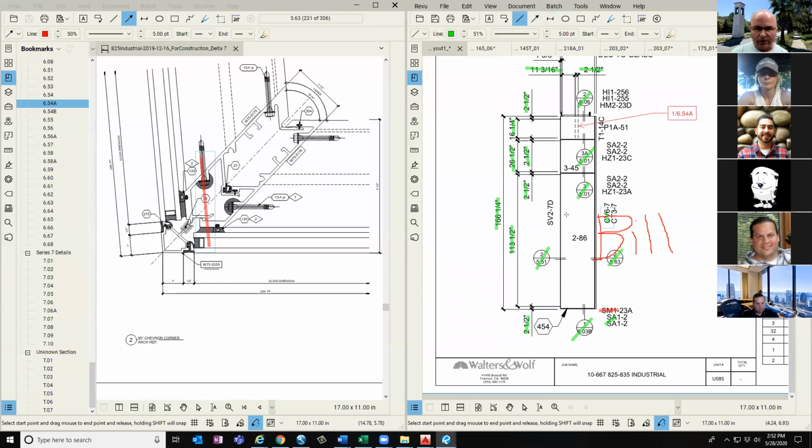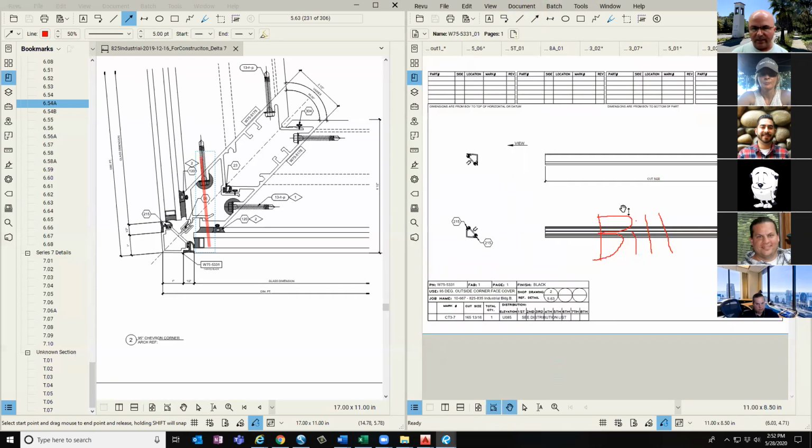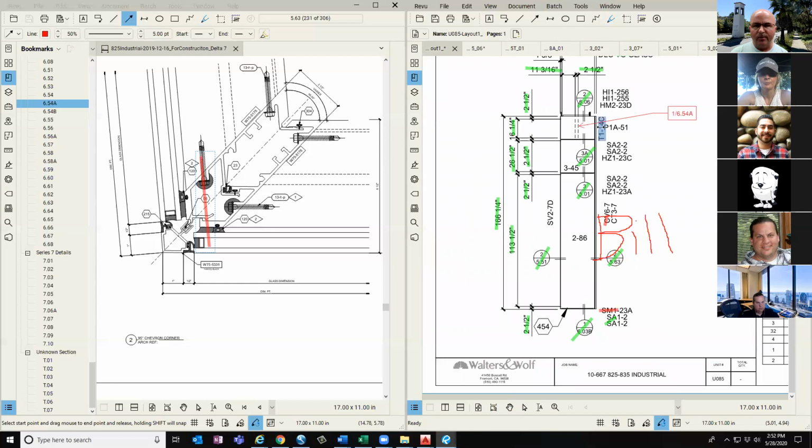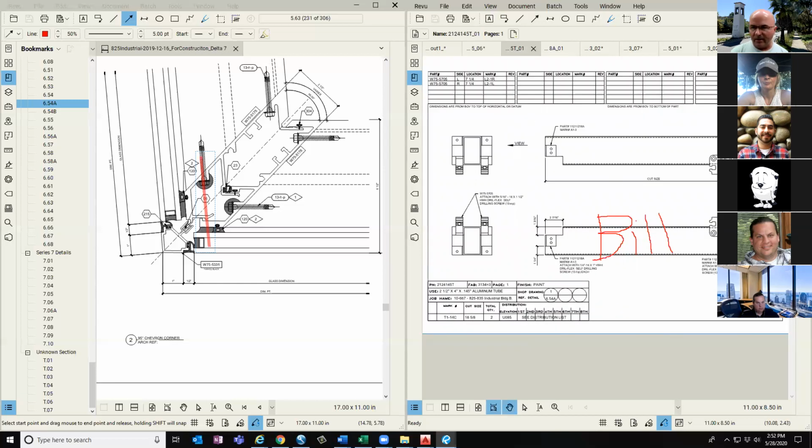Then I'll go to, this is actually red because it's got a problem with it. Then I'll look at the corner trim, verify the length of that. It's actually the same length as the vertical. I'll use the horizontal cuts to make sure that that makes sense of where the corner trim needs to go. Then on the pony tube, I'm going to make sure that the angles are working. We already looked at these when we were looking at how they attach to the head and the horizontal member. And I'll verify these clips. I'll mark those up.